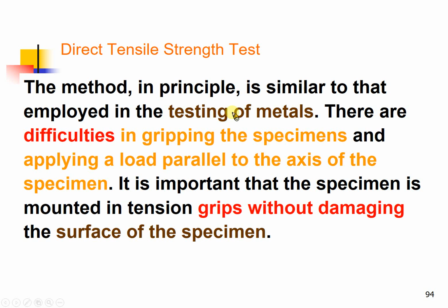Okay? And for the Brazilian test, we're using a disc, and you apply a concentrated load on the edge of the disc. Then you will have a tensile stress within the disc. I will show you the stress distribution within the sample, the disc. So I don't really have time to go through all of them, so I will stop here.